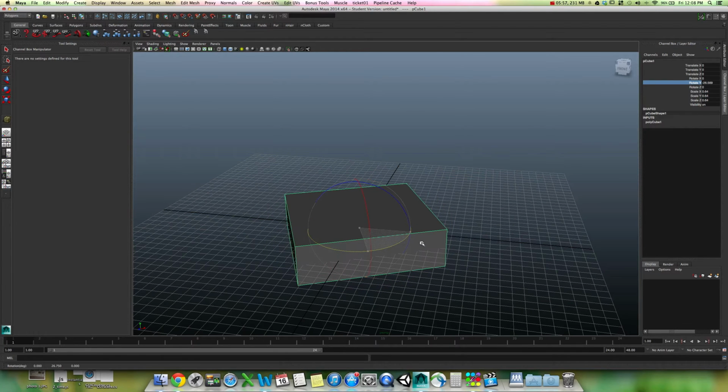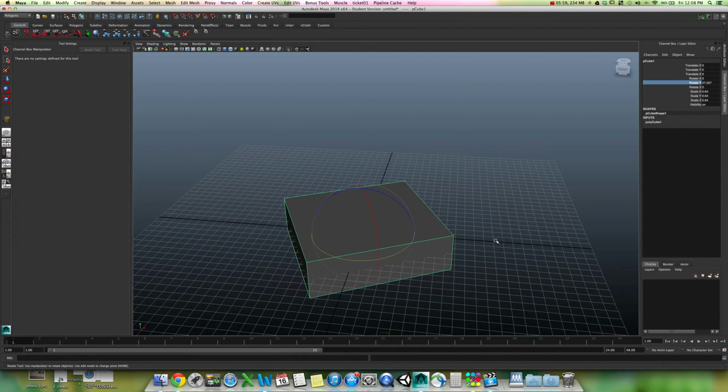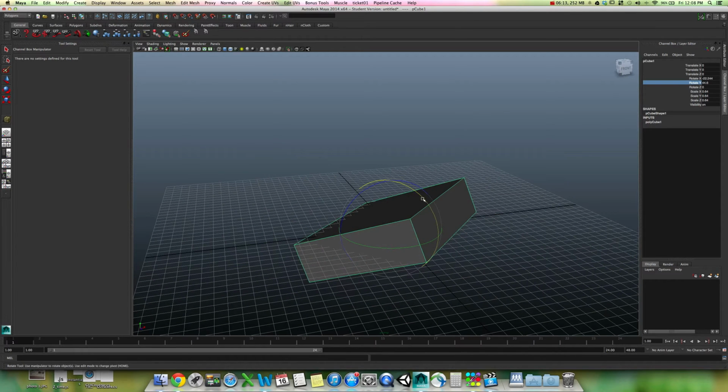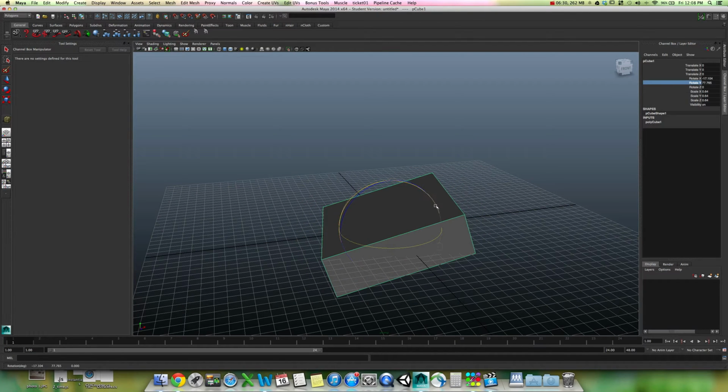Now, this is what we end up talking about when we mean global and local space. There's a lot of stuff about local coordinates and global coordinates, and it takes a while to really understand the difference between them. I'm going to try to do it in a very abbreviated manner, but you can also read about them in the book. But what's happening is these points in space are changing in relationship to the world while maintaining their relationship to one another exactly the same. So they're all moving together at the same rate in the same amount, but they're changing their positions in space, and that's what a rotate is.